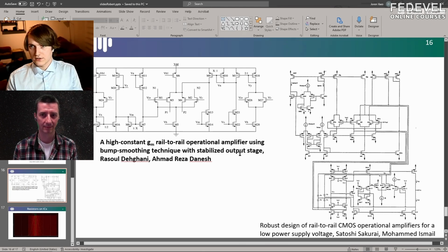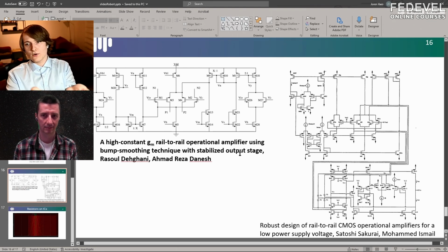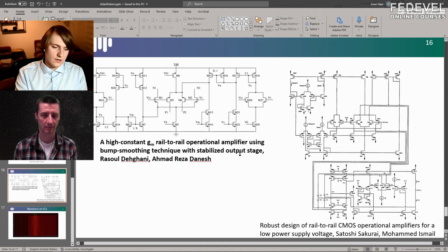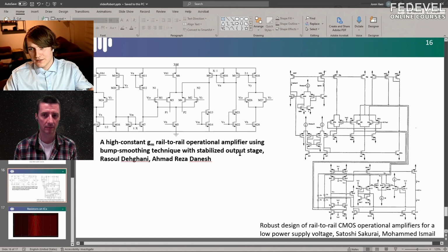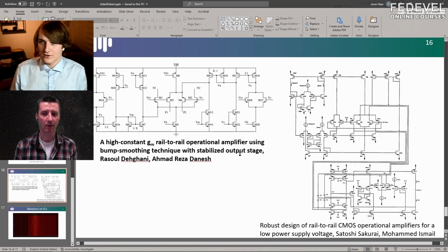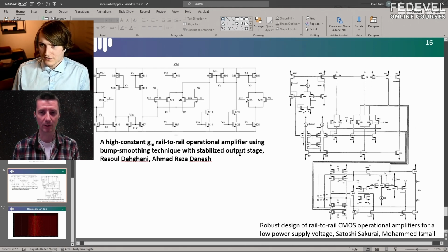Sometimes it's just hidden registers on the chip that might not be visible to you through I2C, but when the chip is powered on for the first time, and then again once it's programmed, they blow the fuses. These are all options, and it goes all the way to a CPU, right, where you have the ability to program new microcode to tell the CPU what to do after the fact, and you can even add patches, and Intel or AMD will give you security updates. Okay, so this is what the microcode does. It actually configures this internal circuit which will adjust the chip parameters. Part of it, yes. Wow, okay, nice.